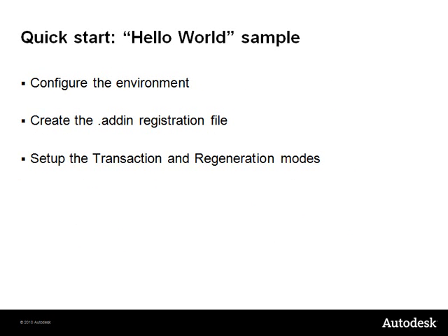Let's make a quick start creating a classic Hello World sample, where we will be able to configure the development environment, create a .addin file at the Revit addin folder, and choose the transaction and regeneration modes.